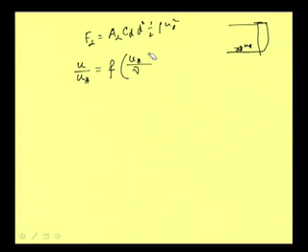In reality it is U star y by nu. Let me write it as U star y by nu first. Y means any depth, U star y by nu. This is the shear Reynolds number. Now, for our case here, we are interested in UD, that is what is the velocity. This expression is general, at any depth y we are talking about this velocity U. Now, our interest is what is the velocity at this top when depth is d.